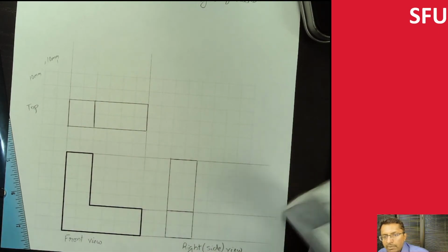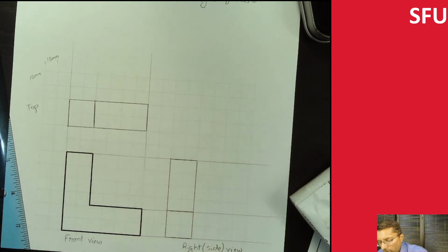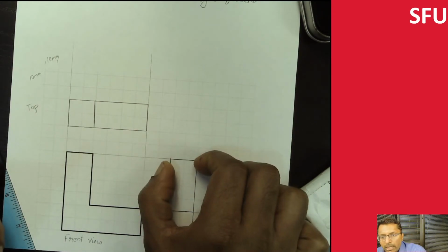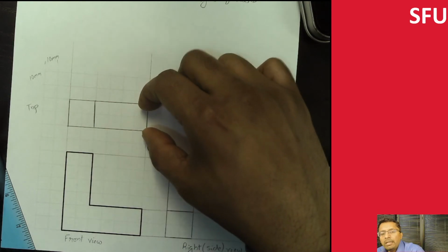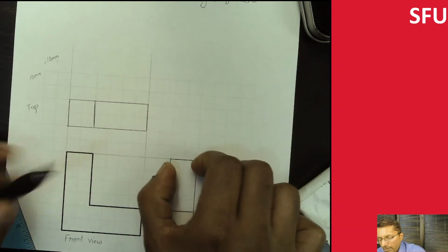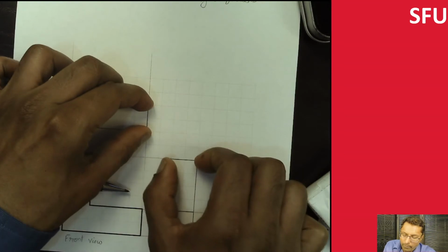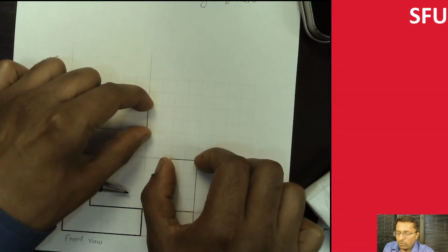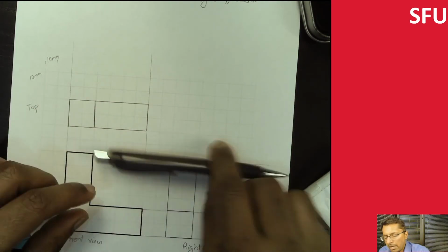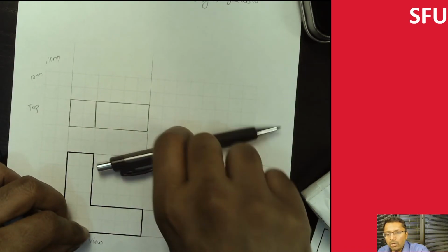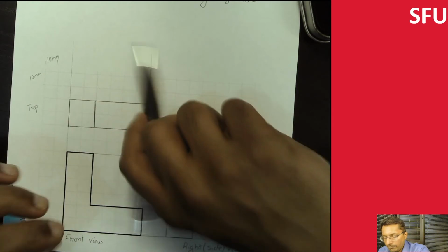Now there is something that's curious, right? If you think about the object, it's 20 millimeters deep over here. So it needs to be 20 millimeters deep over here as well. So essentially, the top and the right view do share the depth information because it's still the same object. But what's actually happening is that it's being rotated by 90 degrees, right?